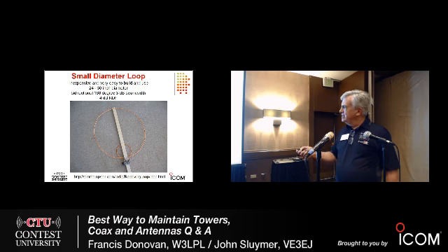So all that's involved in this is 2 pieces of tubing or 2 pieces of wire soldered together at the feed point and a capacitor to resonate it on the frequency of interest. It's a narrowband antenna. And a transmission line that's decoupled that goes to your receiver. That's all there is to it. You can learn how to build it right here. It's a very specialized antenna, but really tiny. And look at the 3 dB beam width of the main lobe, 160 degrees wide. And the deep null is only a few degrees wide, but only for local RFI.